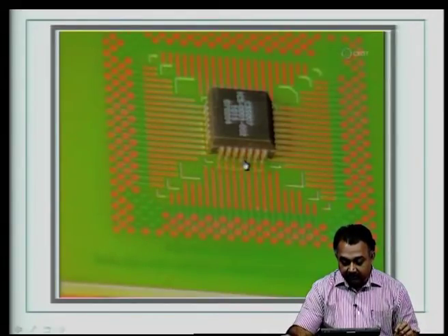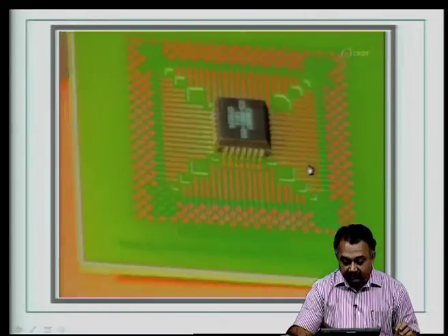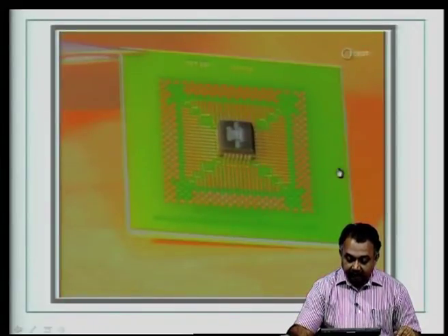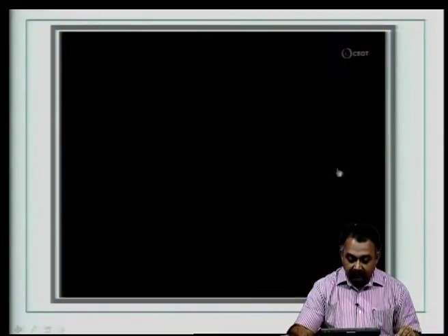There is no solder bridging between the pins, no extra solder, and this resembles a perfect joint that has been generated using reflow, solder paste, and for a J leaded component.